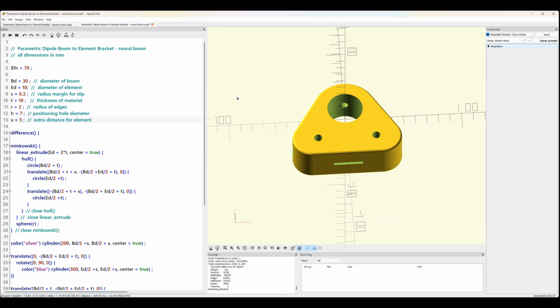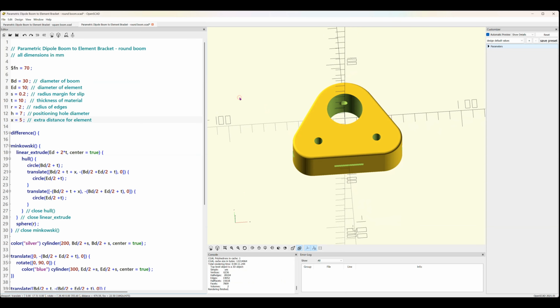To change this to something that the 3D printer can use, we go up to the very upper left, and I know you can't follow the cursor, but look where I'm clicking on File, and then I come down to Export as STL. I click on that, and that gives you the opportunity to save the model as an STL format file.